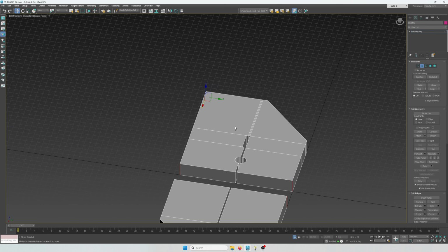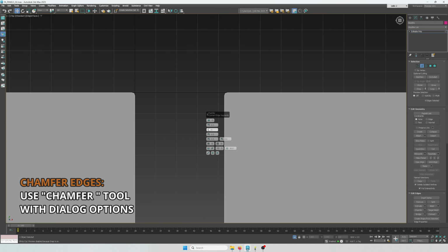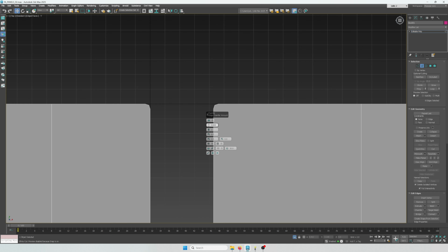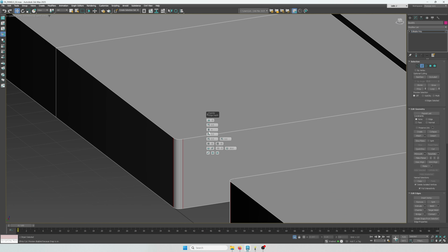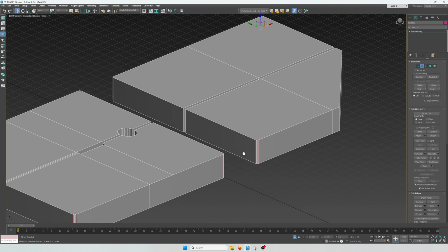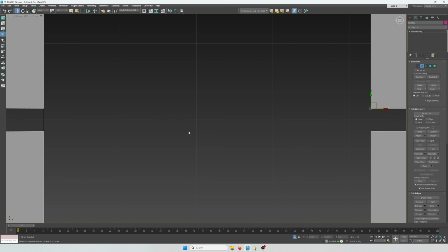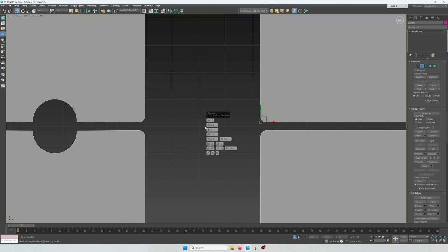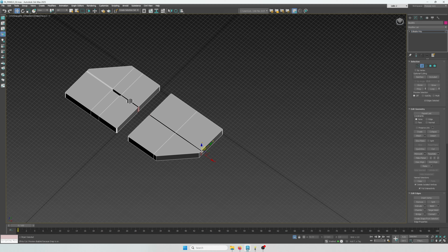Let's select the corners now. These are the corners that we want some tighter chamfers in. I'm thinking about 0.5 as the value. Never mind, the ones that are in the center are gonna be the tighter ones. Let's make these 0.25. And these as well, 0.25.